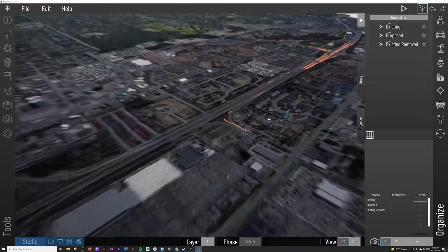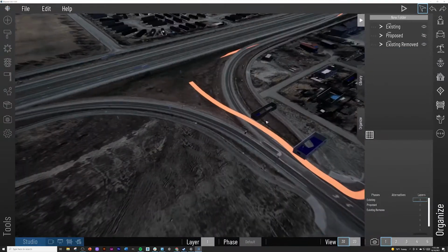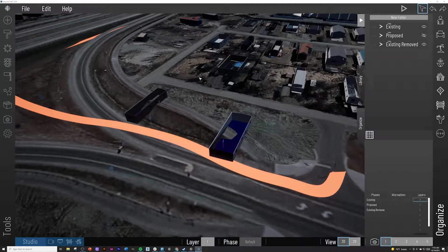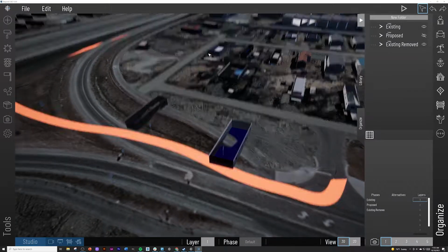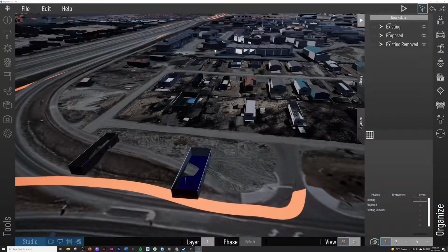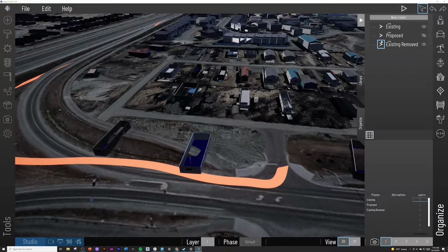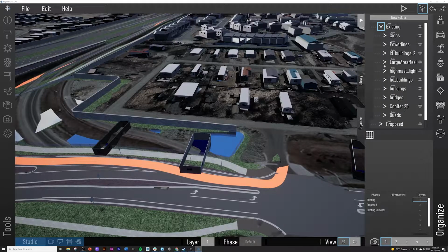All right, so when you go to this area, it looks like the modeling's just off. So we're going to just turn off all these houses and replace them with houses from the asset library. And it's not going to be perfect. In reality, we would probably go back and find that Appliques file and remove those, but we're just going to do it this way. It'll just be a little bit easier for what we're trying to do.